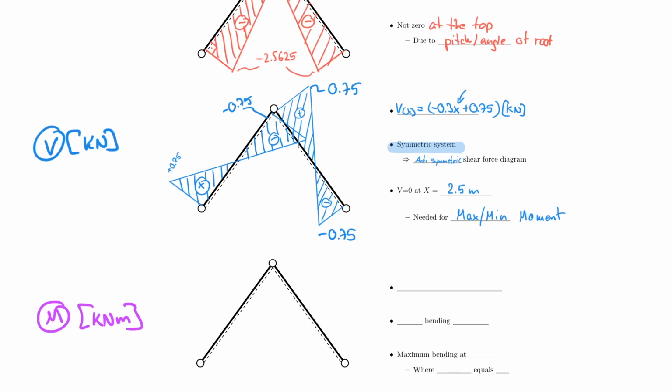Before I do that, I just want to show you that I bring these center points down effectively. But it's important to understand that now I have a perpendicular line which really defines where things are happening. So this would be perpendicular to the rafter itself. And now I can use my basic knowledge about moment diagrams to help me draw this effectively. The very basic thing and first thing I know is that at each hinge or at the supports, I must have a moment that passes through 0.